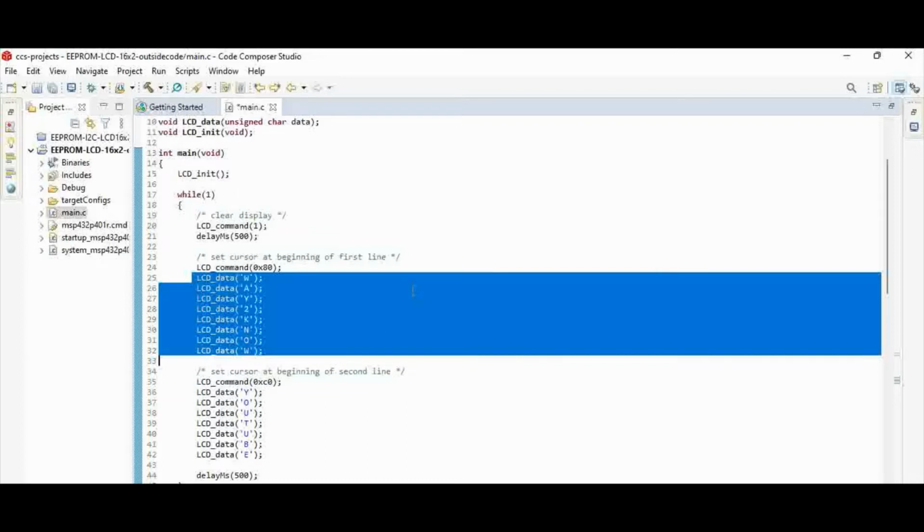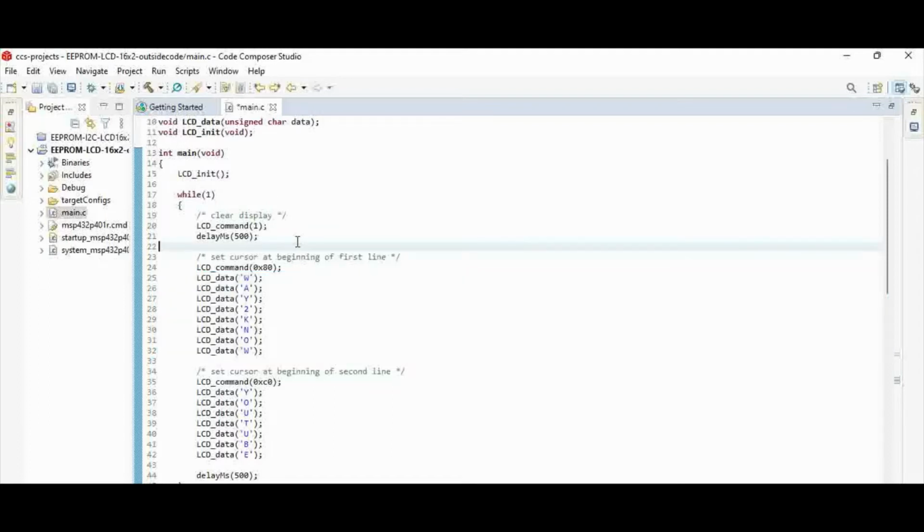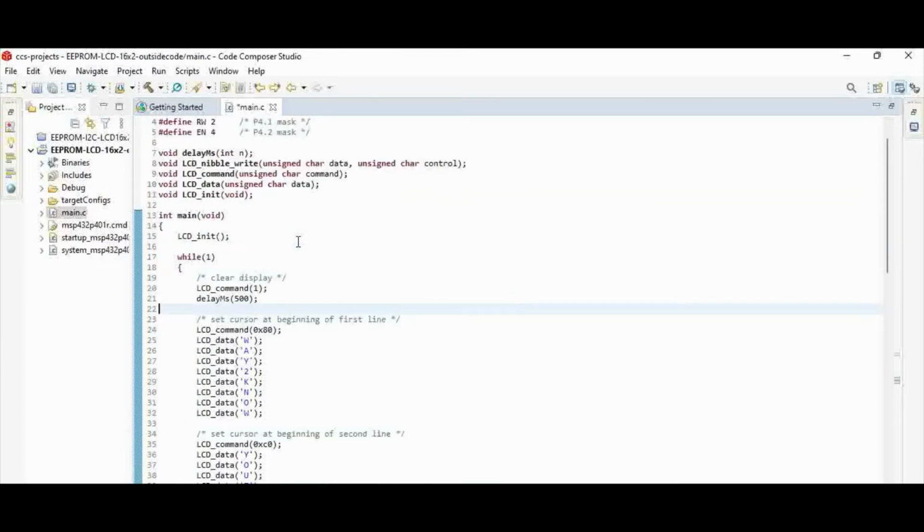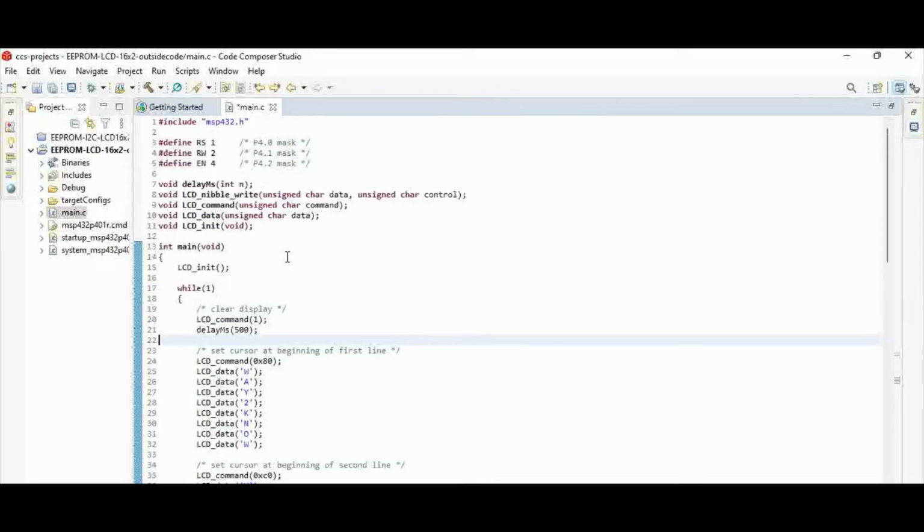One more scenario we have to see is, if you look at the 2x16 LCD, you generally have an 8-bit parallel interface, D0 to D7. You can use the full interface or you can also use a nibble. Nibble means 4-bit, where you can use D4 to D7 or D0 to D3 based on your connectivity. When we say use, we are saying that you are going to interface to your microcontroller using those lines.